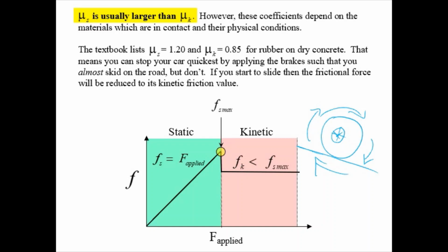So what's going to happen is, ideally, if your anti-lock brakes are adjusted right, you kind of teeter-totter back and forth right over the top of this peak here, and that's actually what you feel when you feel that little rhythmic thumping if you've ever had your anti-lock brakes kick in. It's almost like pumping the brakes. They used to tell you to pump the brakes, right? That was the old-fashioned way of trying to do exactly this: if you hit the brake hard and then release, you're hopefully going over the top of this peak. But of course, pumping the brakes, you could have quite dramatic swings and not as big an effect. If you had a computer controlling it, you could stay right up near this peak and get some extra friction.